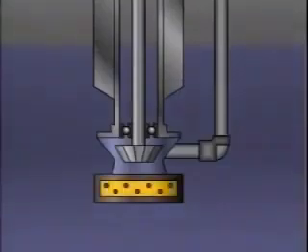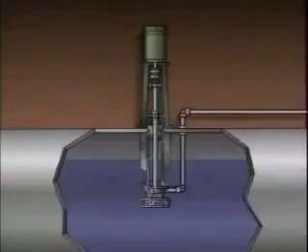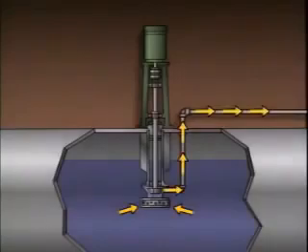The suction is covered by a strainer, which prevents trash or debris from clogging the pump and causing excessive wear. The pump's impeller is also submerged in the liquid. This helps to ensure that the pump is always primed. This means that the casing is filled with the process liquid. During operation, liquid is drawn in through the suction and then pumped through the discharge piping, which extends up and out of the tank.